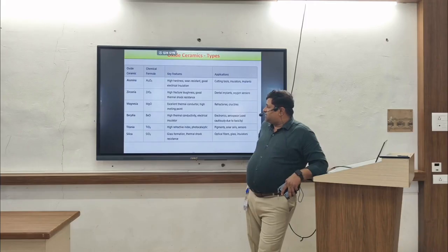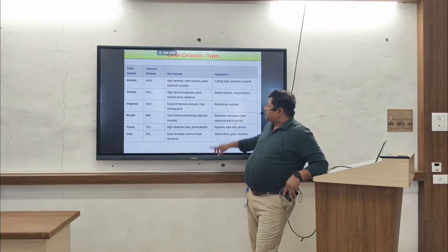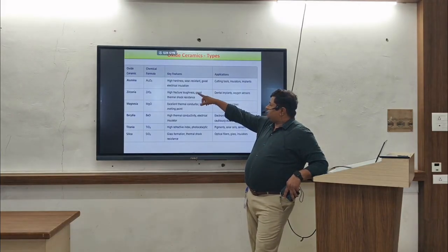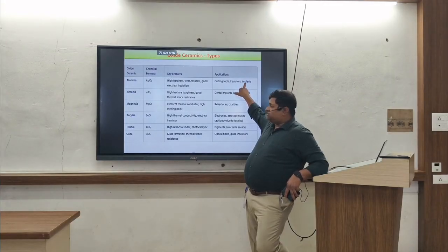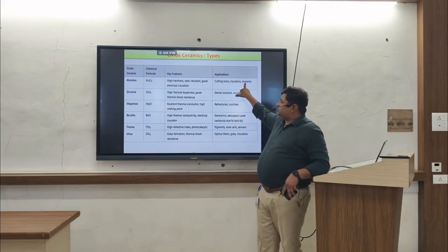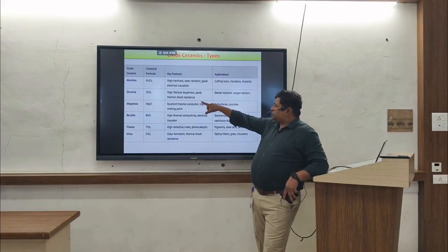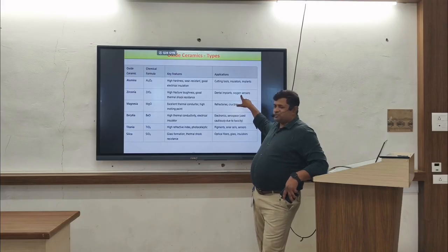Alumina is there, zirconia is there, magnesia, beryllia, titania and silica. Al2O3, ZrO2, MgO, BeO, TiO2 and SiO2. Their key features: Al2O3, high hardness, wear resistance and good electrical insulation. Applications in cutting tools, insulators and implants. Like we can have bones made from this particular alumina oxide ceramics. Zirconia, you can see high fracture toughness, good thermal shock resistance, dental implants and oxygen sensor.